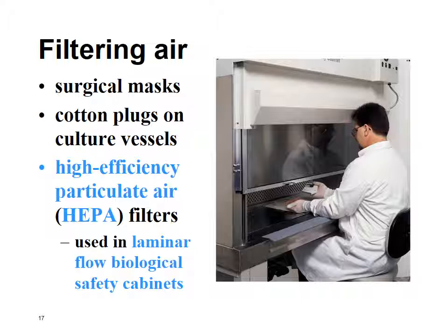Laminar flow biological safety cabinets, otherwise known as hoods, force air through HEPA filters, then project a vertical curtain of sterile air across the cabinet opening. So this protects the worker from microorganisms being handled within the cabinet, but also prevents contamination of the room.